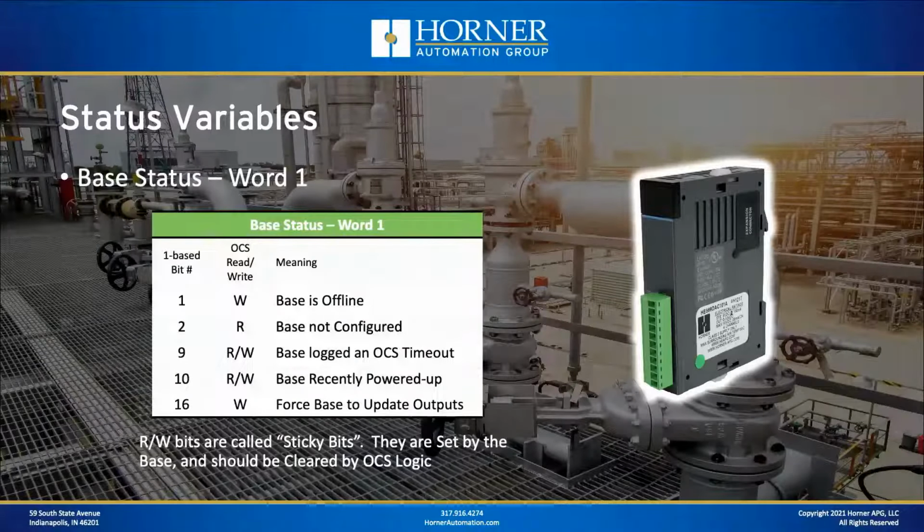The base will set a flag so that when they start talking again, the OCS will know that, hey, I was talking to you, Mr. OCS, and you went away. That is what's called a sticky bit, which means that after the OCS sees that bit being on, it has the ability to clear that bit by writing to it.